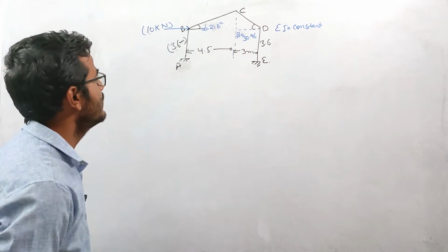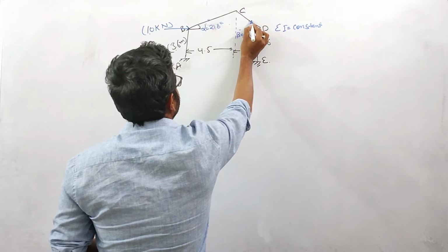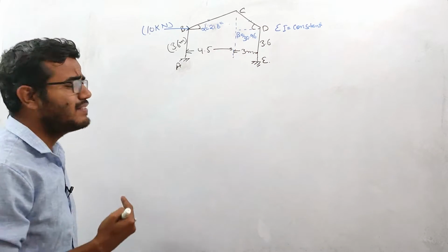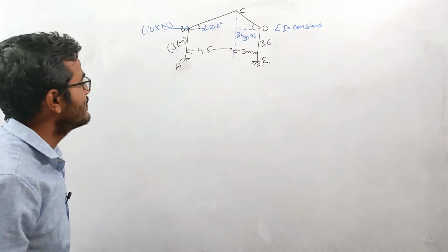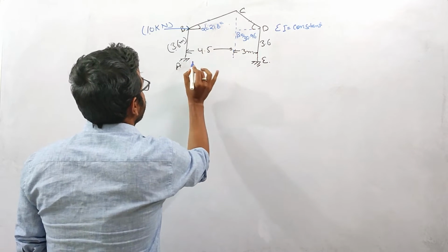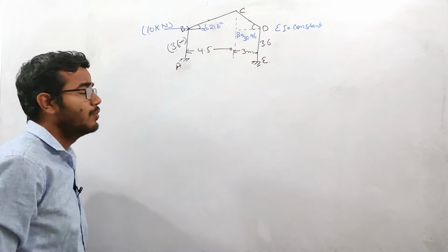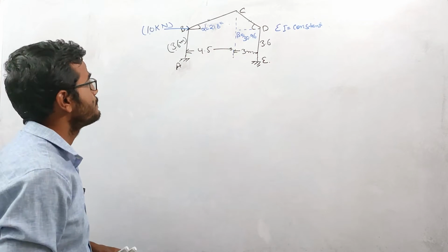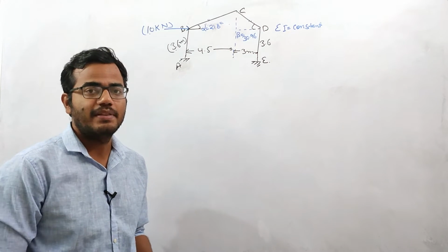This is the gable frame structure. As you can see, here we have these two sloping sides, and this is the apex point, right? This type of structure has industrial use basically, and these types of structures are used where the span required is large. Here you can see that the clear span is 7.5 meter. In those types of cases we will be using this type of structure. So we need to analyze this structure by using the slope deflection method.